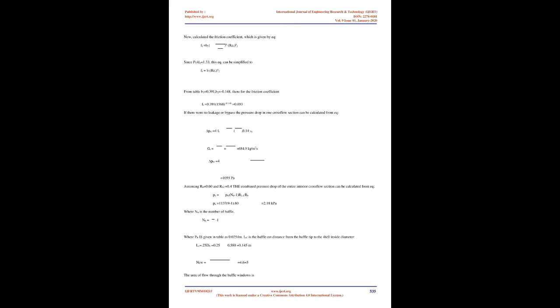The arrangement of the dividers in multiple pass exchangers is somewhat arbitrary, the usual intent being to provide nearly the same number of tubes in each pass, to minimize the number of tubes lost from the tube count, to minimize the pressure difference across any one pass divider, to minimize leakage and therefore the violation of the MTD derivation, to provide adequate bearing surface for the gasket and to minimize fabrication complexity and cost.